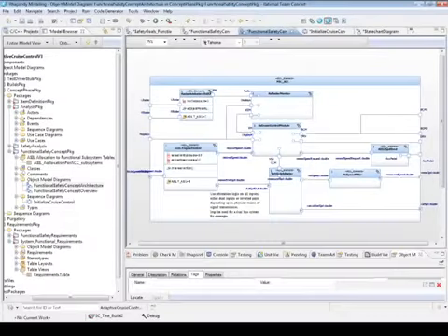Now that Mark has completed the safety analysis and pushed the safety requirements and safety goals back into DOORS, these provide the inputs for Dan to carry on and develop the functional safety concept. Here is the detailed architecture. It has the same elements as was used previously: the radar monitor, the cruise control and the engine control. But in this instance, to add safety, we have a radar arbitrator, which is looking at the difference between the left and right hand radar signals, and a vehicle speed arbitrator, where we're looking at the input from two different types of sensor on the wheel and making sure that they're the same.